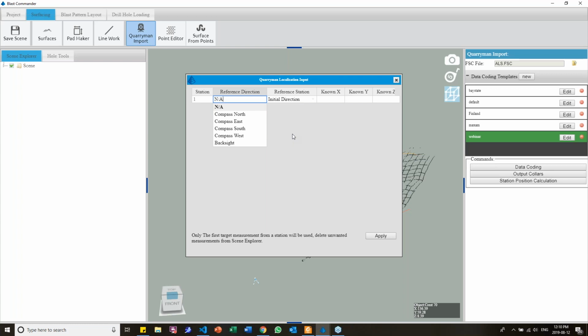All you have to do is input the bare minimum amount of data, getting at least one position and one direction, which you can actually do simply from the control points, and it will align and solve for the system automatically, which of course is not necessary in this particular set. Because we're in a local grid, we only have the one station. We could leave everything as it is right now. I just wanted to touch briefly on that, and thank Julian for the quick explanation there.